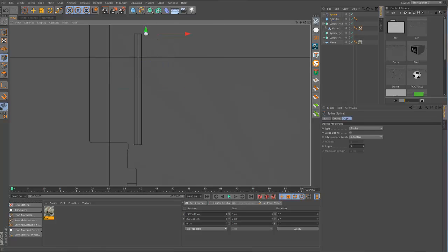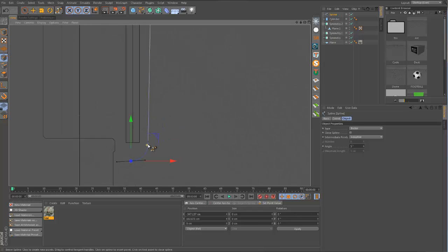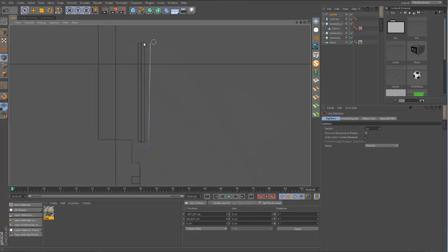I'm going to start at the top here, go straight down, and then draw like a curve. Okay, I pressed shift and that basically snapped the direction of the spline to the starting point. So when I clicked the next point, it kind of created a wrong edge. But anyway, if I click here, I can make a nice curve like this, and then all I need to do now is to make sure this point is on the same X position as this point down here. So this is -331. I'm gonna copy that and paste it over here, so we have a nice straight line with the curve at the bottom here. Can maybe just pull that in a little bit.